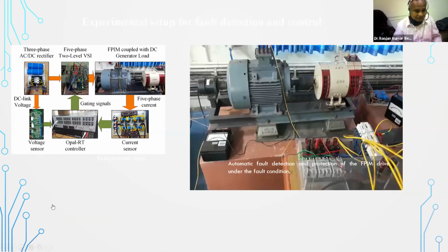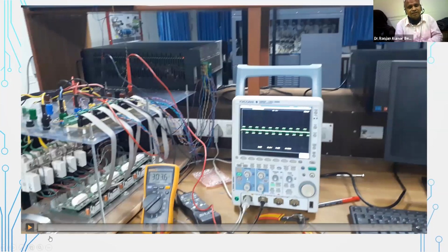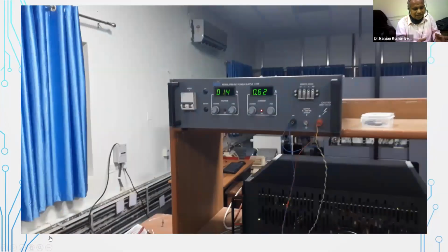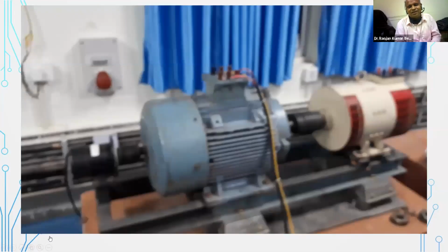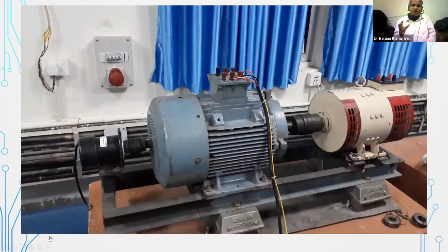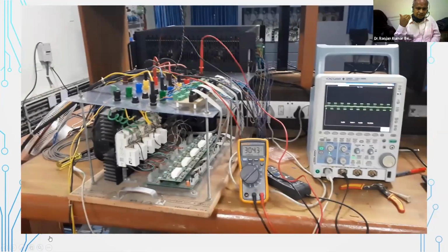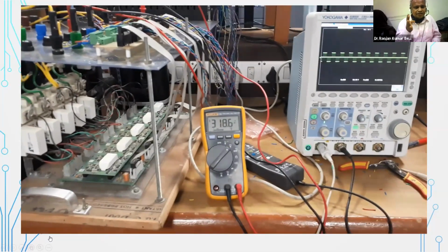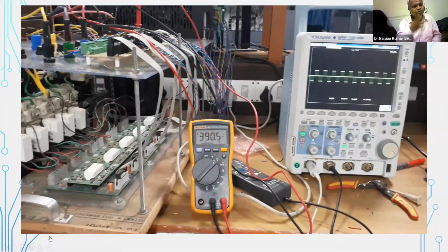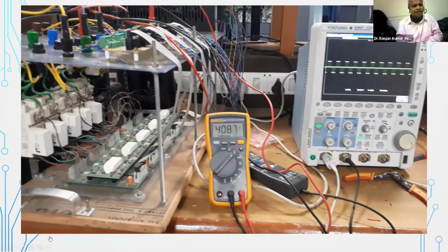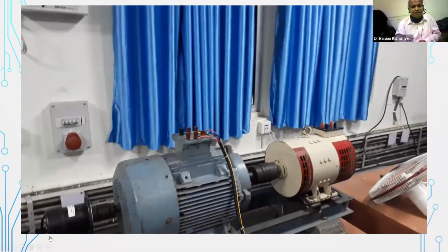We also tested this one. This test is for this five-phase motor. You can operate it down to four phases, three phases. You can see that this motor, by using different switching techniques, can operate at three phases, even four phases, like that. We are feeding it from three-level and two-level inverters, both ways. You can see that this inverter is working perfectly.